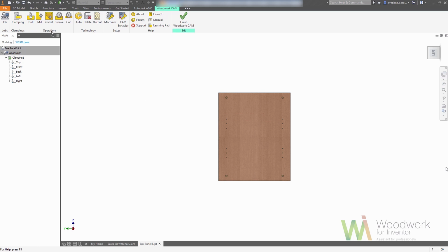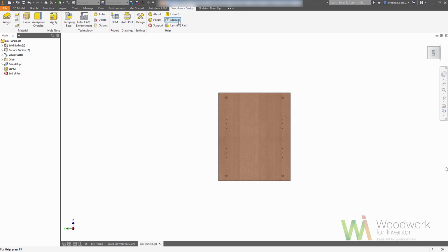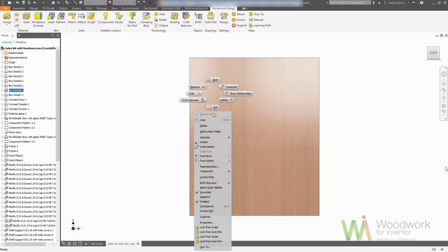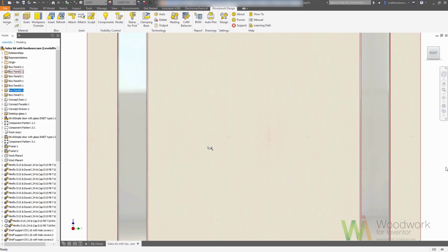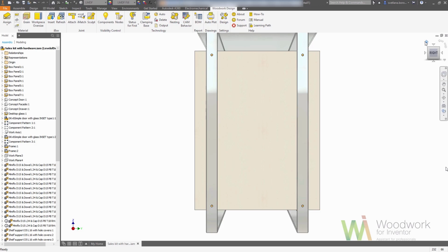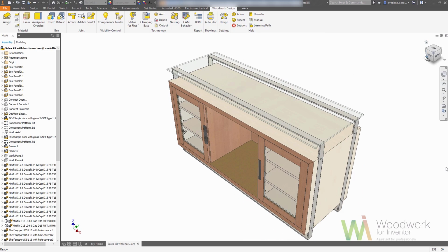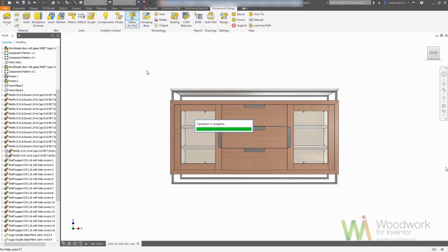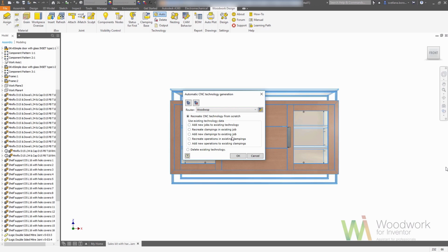So now we are doing the technological operation, and you saw in green that there are drillings available to do with the current setup, including the tool set, according to the spindle setup and the machine setup that we had. So we made those operations. Now we are going back to the assembly, and as you can see, this green indicator showed that one part has the technology already made.